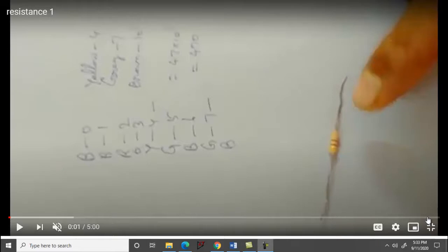The rest of the pins available to us are 12, of which 3 pins are for a gate. So for a 2 input AND gate, 2 pins are for input and 1 pin for output. So you will have 4 AND gates in the 7408 IC.